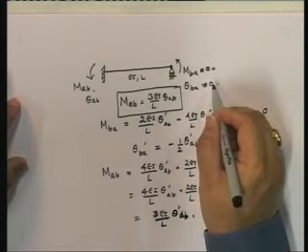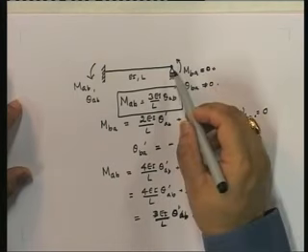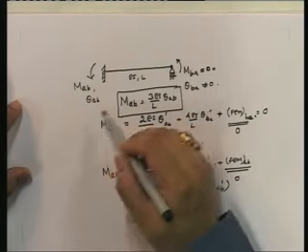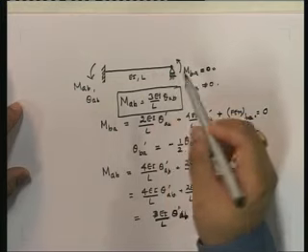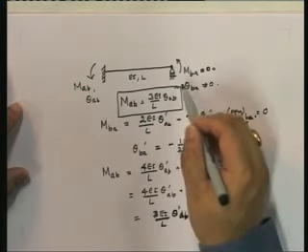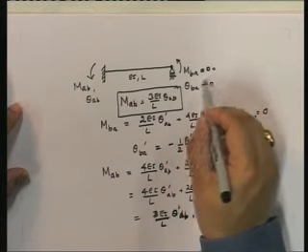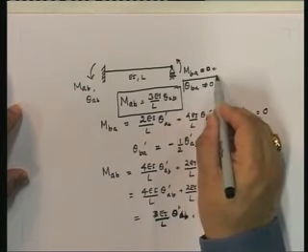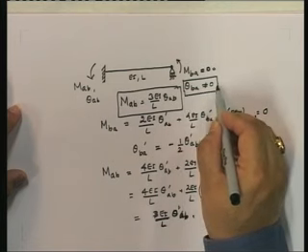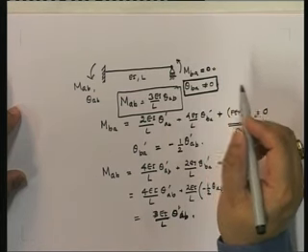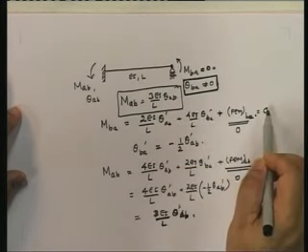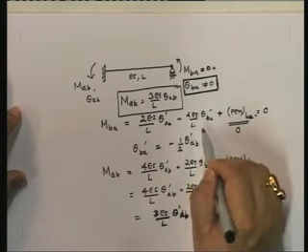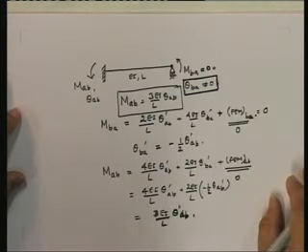Well, it doesn't really matter in this particular case, because remember that the only reason why we are finding out rotations and displacements is essentially to find out the moments. And since you know that the moment over here is 0, you really don't need to find this out at all. However, if you are really interested, you can always find out what theta AB is equal to from this formulation.